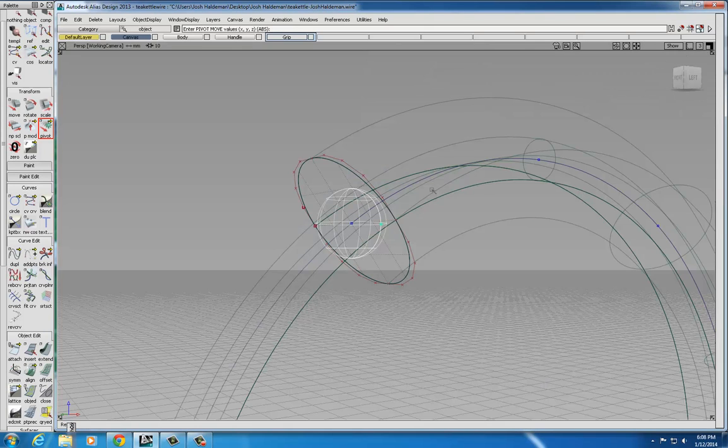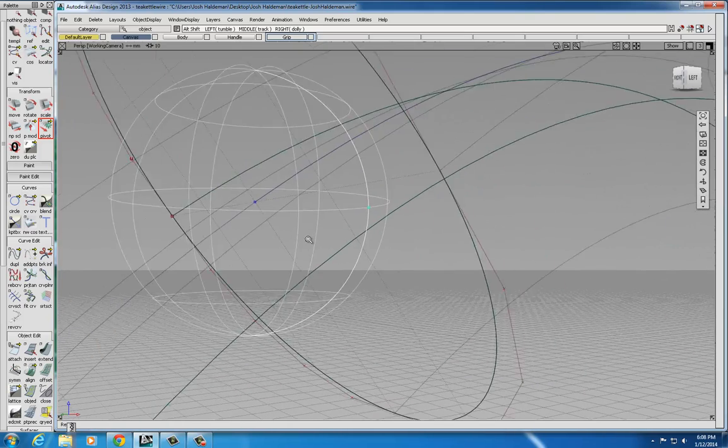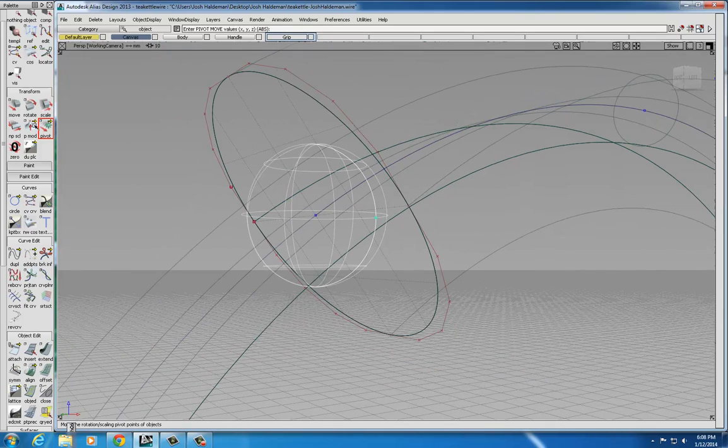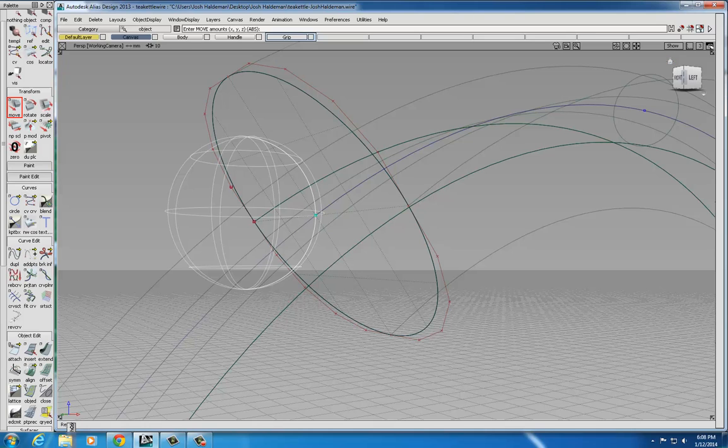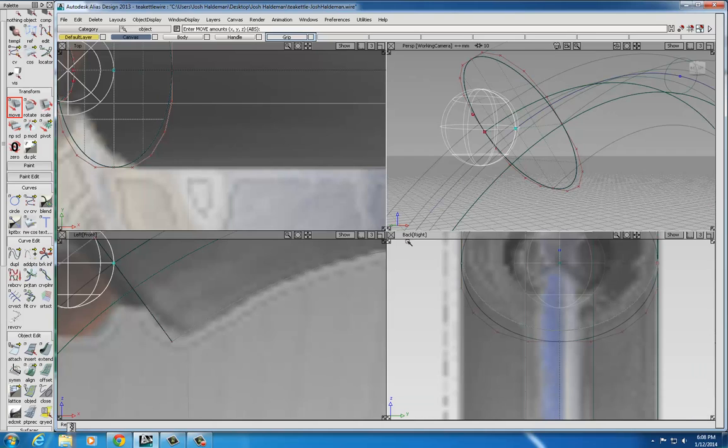Then I'm going to go back to my perspective window. It's important to have the flexibility to jog between views. And then choose the Move tool, and again click the same line that I clicked to initially place that sphere. What it'll do is move the object because it's moving it in relation to where the pivot point is. So now I've moved it out so that the entire sphere rests outside of the grip.